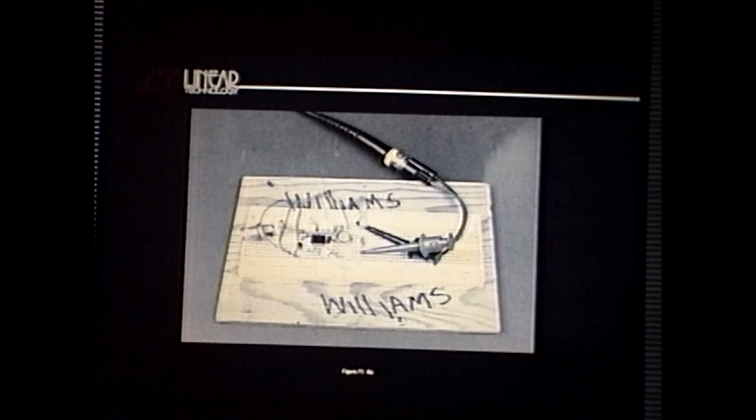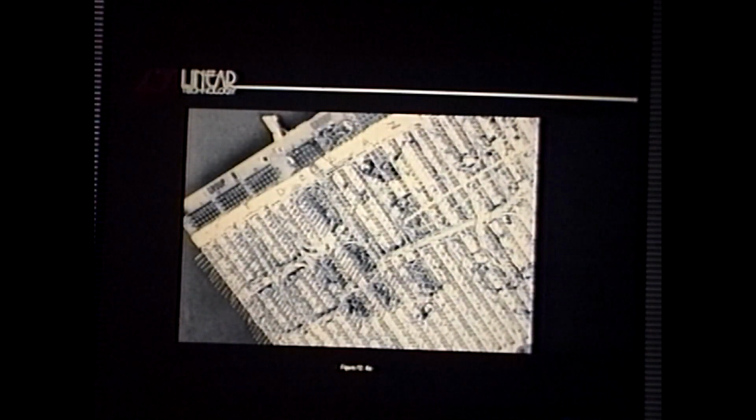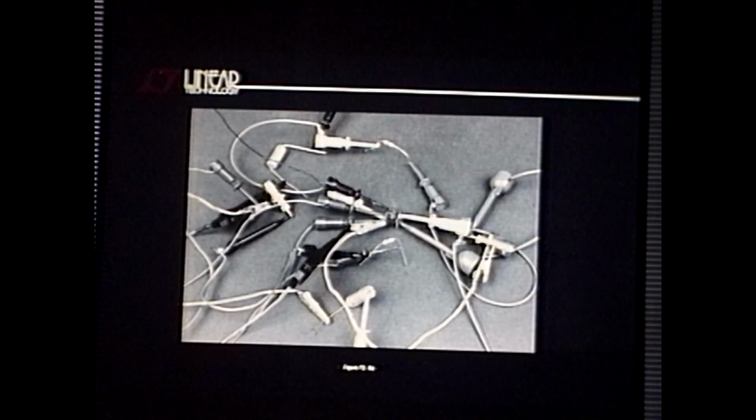This circuit technique is not recommended at speed. Don't do this. If I had my way, all the L sockets ever built would be in the bay. They're terrible. We get stuff like this in the mail. Don't do that. Yes, people do try and wire wrap 100 megahertz 12-bit circuits. Don't do that. This is a customer I spent 3 phone calls and half a dozen faxes with, and when this arrived in the box, I almost fainted. Yes, people do that. They don't understand why it won't work.